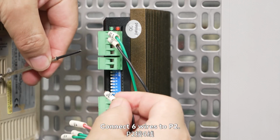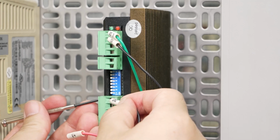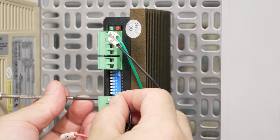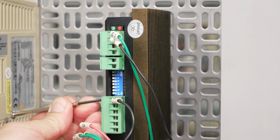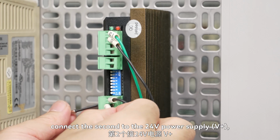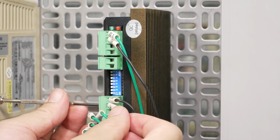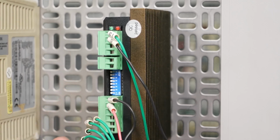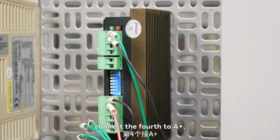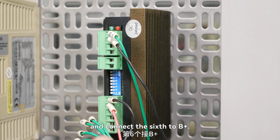Connect 6 wires to P2. Connect the first to the ground wire. Connect the second to the 24 volts power supply voltage plus. Connect the third to the A-, connect the fourth to A+, connect the fifth to the B-, and connect the sixth to B+.